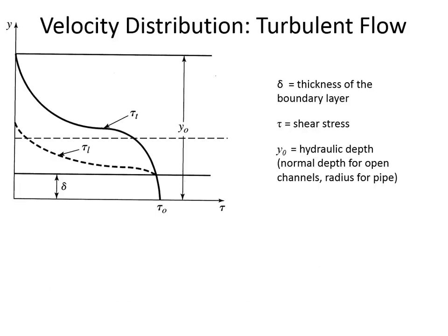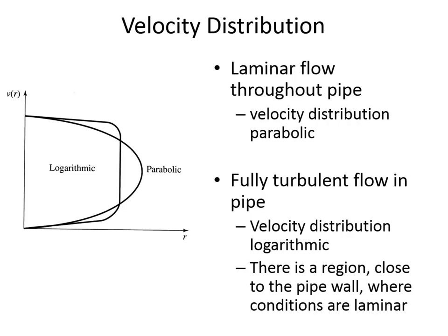So no matter how fast the water is going above it, there is a zone where, because there's not just one velocity in a pipe. Remember, there's lots of different velocities in a pipe. So it is how far away from the pipe you can go and conditions are still laminar. Above that, the Reynolds number is above 2,000 because the velocity is high, but there's some certain thickness. How far is that thickness where you can go and the velocity is still such that you have laminar conditions?